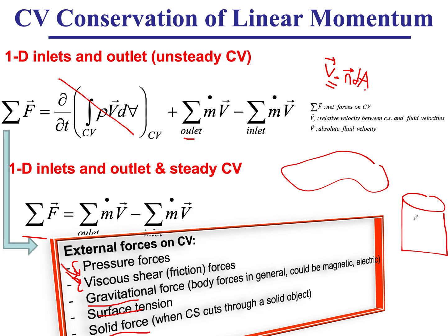If I take a control volume, or actually a control surface, so I could have this being my control volume, but I'm considering the straight line as my control surface. By taking this control volume, you have thrown away the rest of the cup, and you kept this fluid that's within the imaginary boundary that you have drawn. And for that, you now really need to include the effect of what you have thrown out on the control volume that you have. So the fluid that's right over here